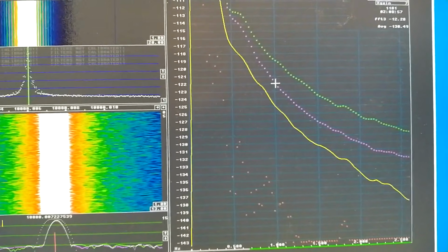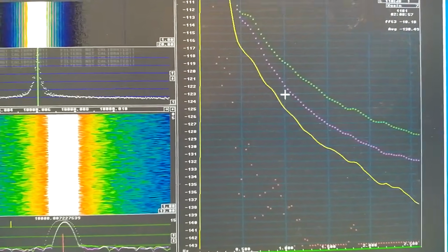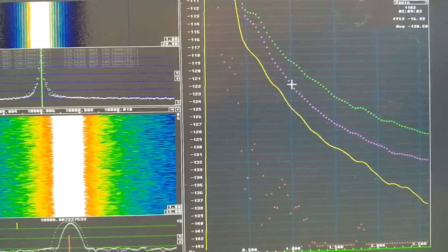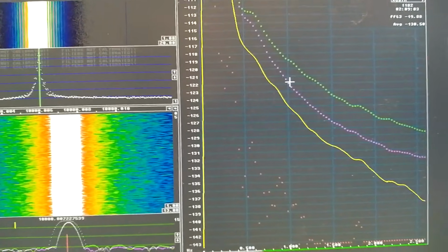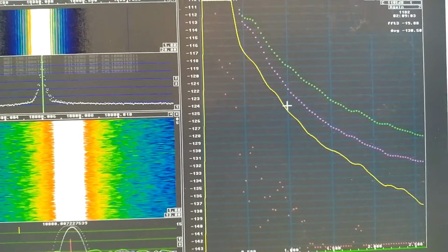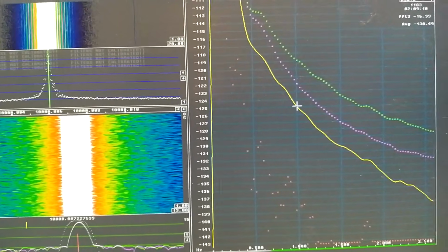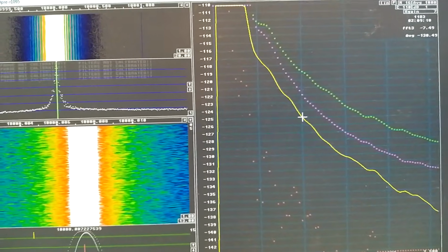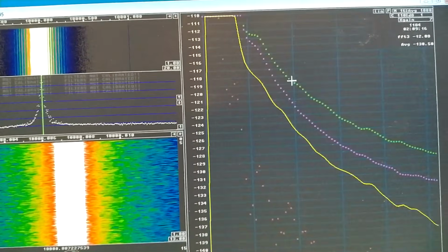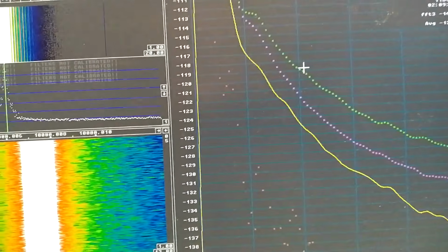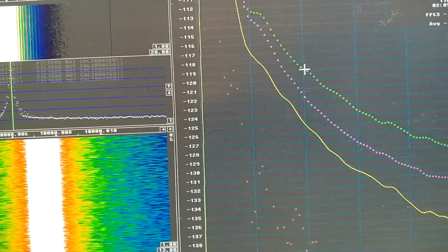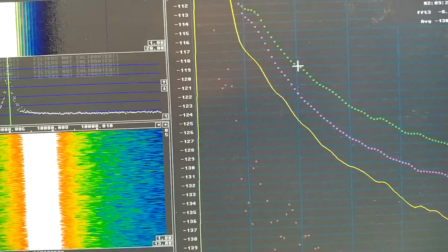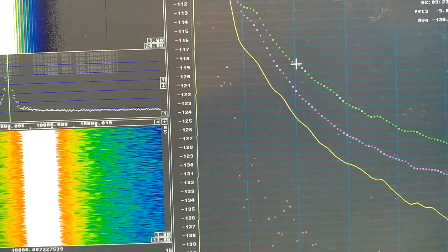That is a difference of 3 decibels, which means that the reference oscillator in my channel 2 is equally good as the oscillator under test at -125, while the Wenzel oscillator reads -119, and I know from old measurements that it is -120.